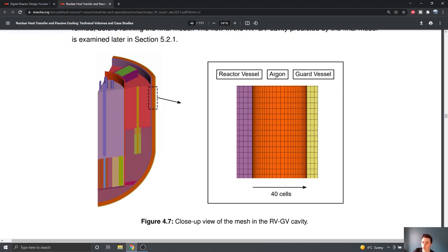So what I've got here is, you can see there's a really high quality structured mesh all the way across, and we've got the thin cells right on the wall there. And those very thin cells, for those of you who've done CFD meshing before, we'd really like to get a low Y+. If we can get a Y+ of around 1, that would be perfect. And the reason for that, of course, is the thermal boundary layers are going to be extremely important for getting the recirculating fluid right in this region.